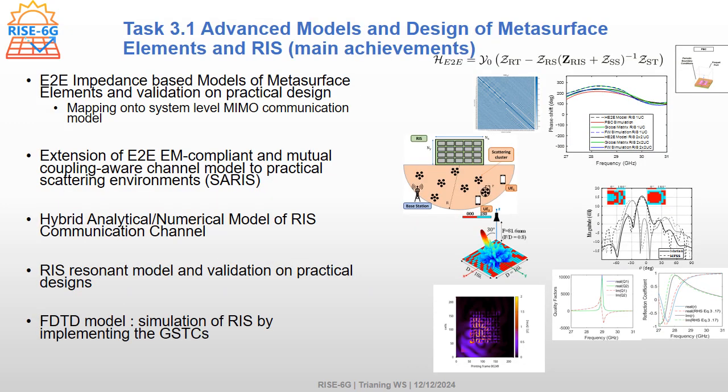Concerning the first objective, we developed an end-to-end impedance model of the metasurface element, which was validated on practical designs and also mapped on a system-level MIMO communication model. This was also extended into an end-to-end electromagnetic-compliant, mutual-coupling-aware channel model for practical scattering environments. This is the so-called RIS.